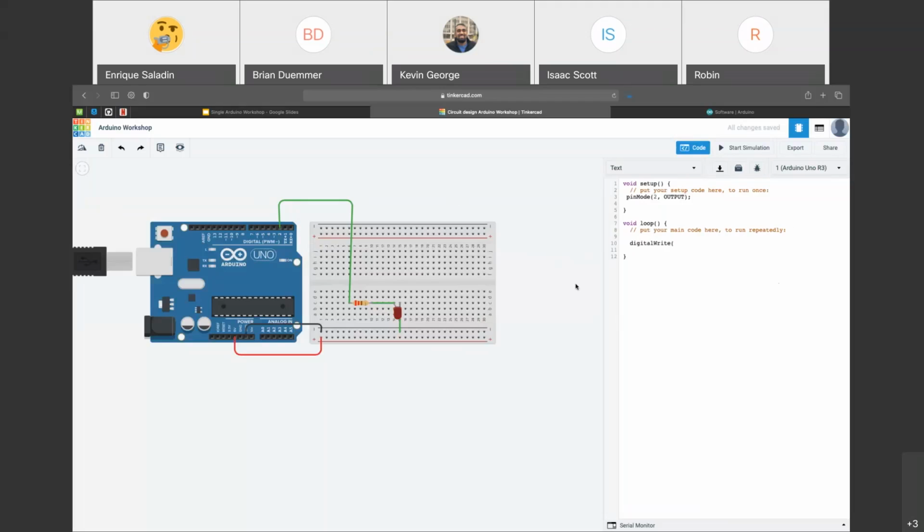This states that we are writing on that digital input and output. We're going to declare a value, so that's pin 2. We're going to do a HIGH. So you get either LOW or HIGH with digital inputs.